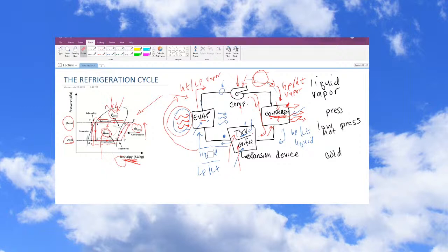So then I say, well, I know that the cam gears work. I know the cam is advanced. I know the sensor's working properly. So therefore, I did have a situation where my camshaft was over advanced for a period of time, and then I can go in and change the valve or do whatever I need to do to continue the troubleshooting. So it's important to me that the guys have a good understanding of how the systems tie together. But at the same time, I like when they have a base knowledge of how the systems work in the first place, and that's always super handy.